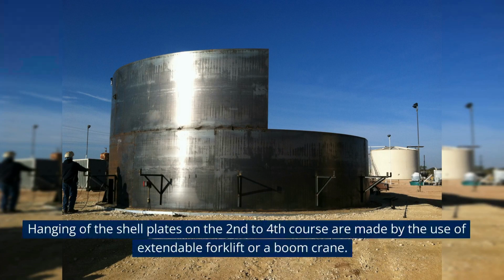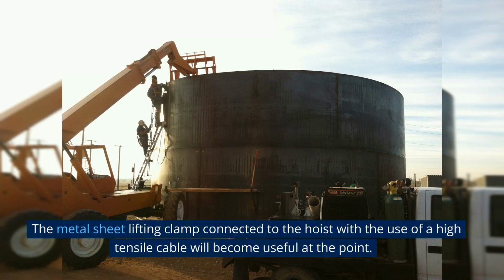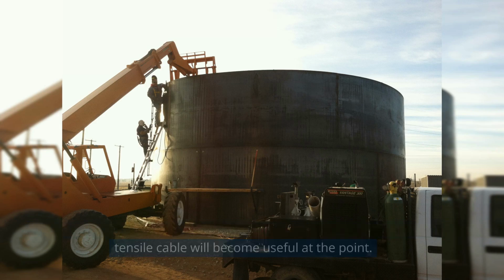Hanging of the shell plates on the second to fourth course is done by the use of an extendable forklift or a boom crane. The metal sheet lifting clamp connected to the hoist with the use of a high tensile cable will become useful at this point.